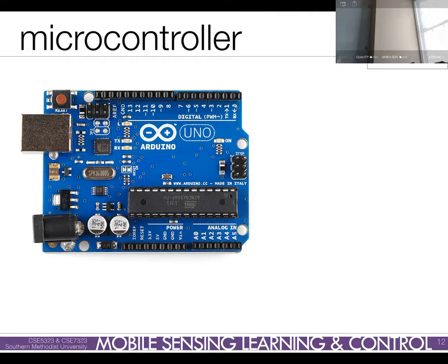It's probably a voltage regulator, which essentially takes, when you put some voltage, say, on the input of this Arduino, let's say you could put 9 volts in, it's going to regulate that down so that the board has 5 volts or 3.3 volts or whatever it runs on. And all of this circuitry there is usually just to help that out.